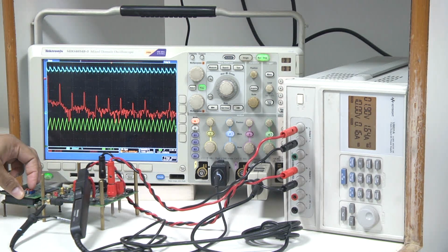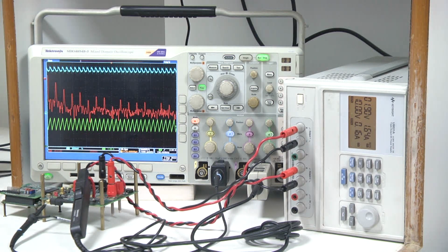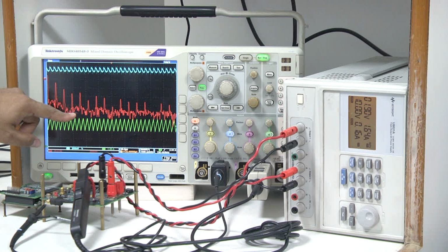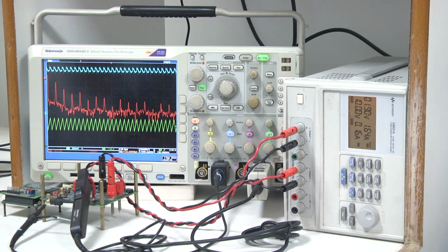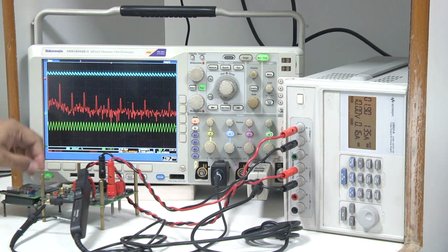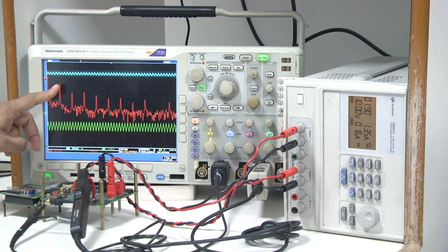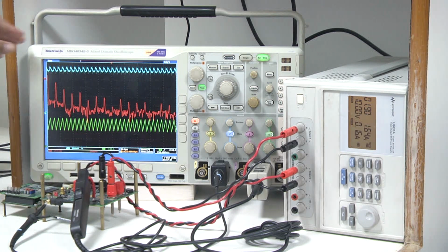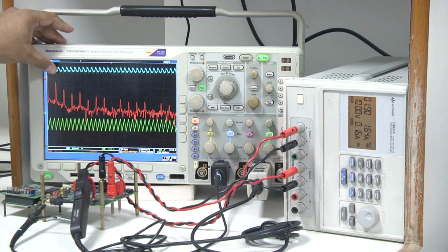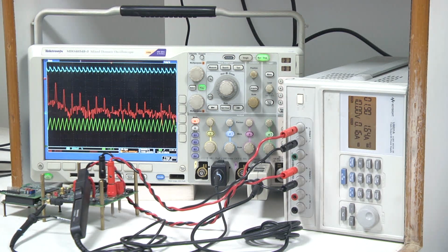Now under the same condition, we are moving to constant off time control, and this is a switch. If you change this button, it moves to constant off time, where we have maintained the peak current, and this peak current is maintained at 3.4 ampere. Now we are starting with 1.9 volt input, that is the least input voltage, and you can see in this condition, when you switch from constant on time, where the frequency was roughly around 250 kilohertz, when you go to constant off time, the frequency has become like 150 kilohertz. That means it is lower than 200 kilohertz, which is the nominal frequency that we set.